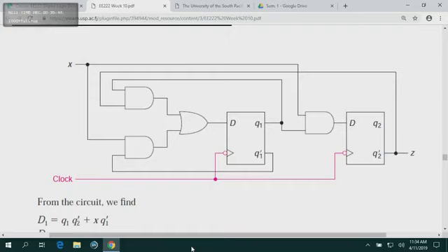Once again, let's look at flip-flop number 1. We want to find out what is D. What is D equal to? What is being fed into D? All right. So, let's do some tracing. The OR gate is connected to two AND gates. Let's look at the first AND gate, the upper AND gate. The first AND gate is what? Z and Q1. Yeah? Z and Q1.